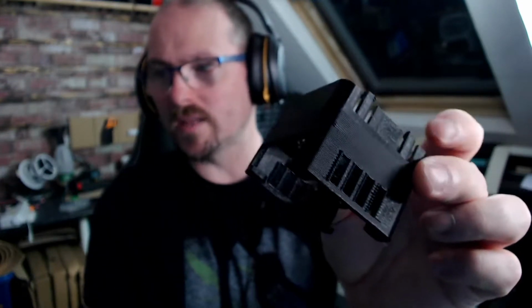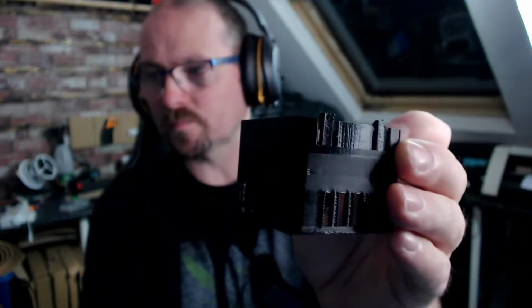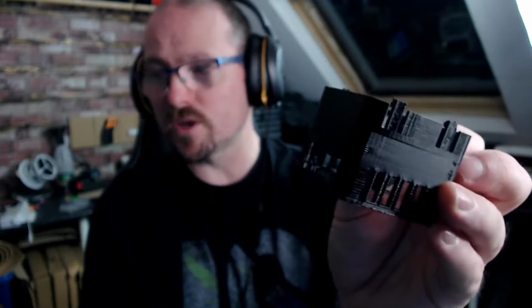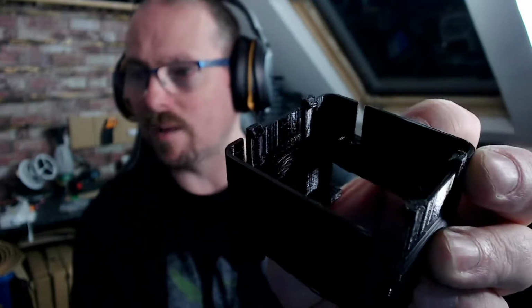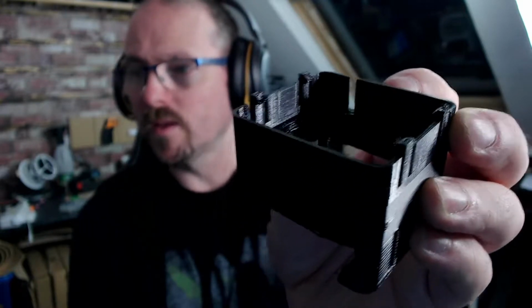The bottom section of this unit has been 3D printed in a very coarse layer height. But in the upper section, where the clips exist, that's actually been printed in 0.2. The reason I've changed the resolution on the height is to make sure that the clips themselves, the overhangs, are created properly and we don't get any problems. If I can try and hold that in camera shot. Come on, you noob. Oh, dear me. What can I say? So there is a 3D object that I printed.